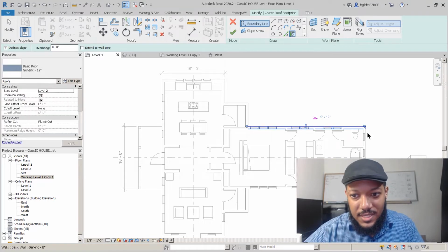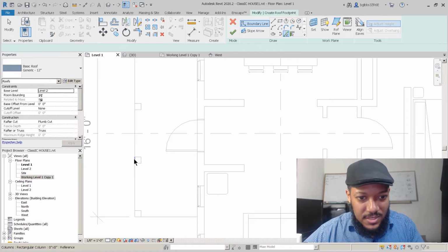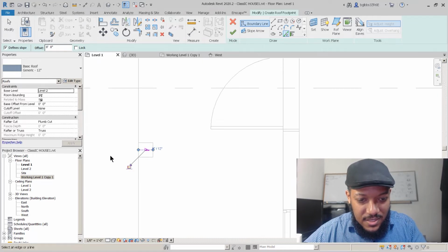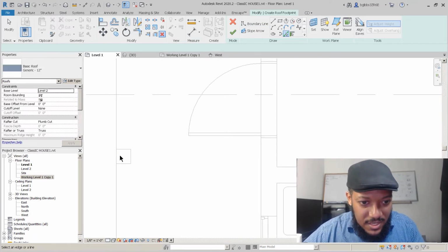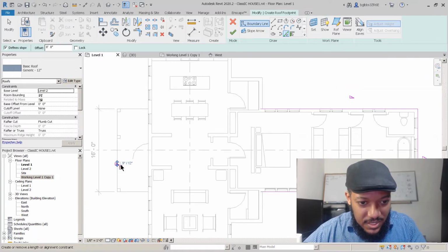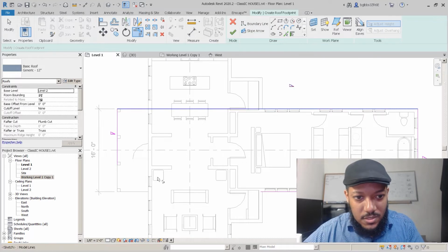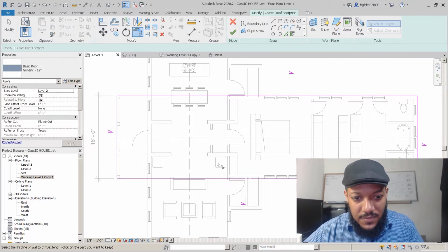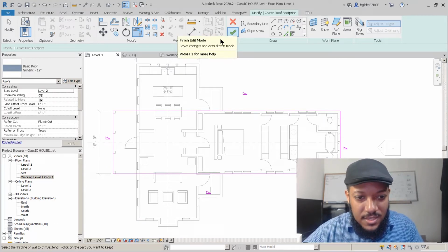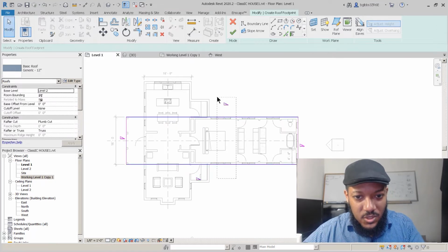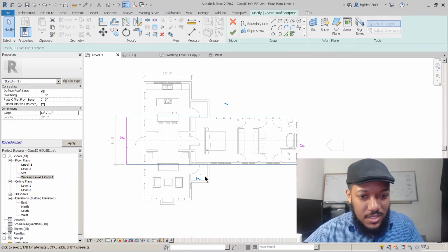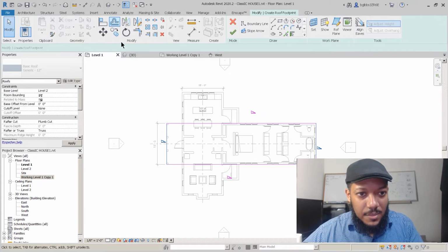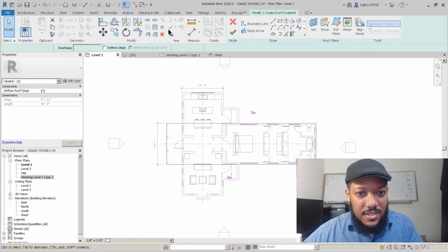And we're going to select the edges again. And this time we're going to select that. And make sure that we have the right line. We're going to constrain it right there so that when we move it, just like with the walls, it will be constrained. So we have those items, and we're going to make sure that these two slopes in our roof are 12 on 12, and this is also a roof family, and we'll look at some of the construction shortly. And we're going to make our ends gable ends, and they are not going to define a slope.